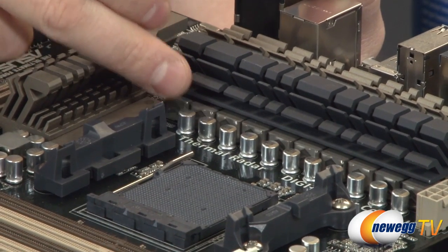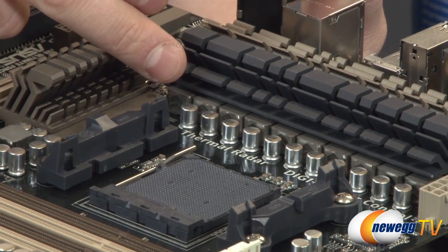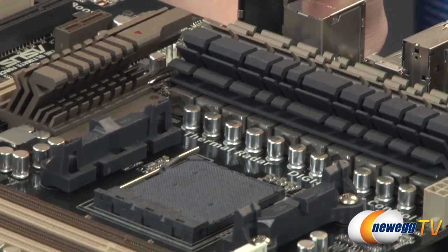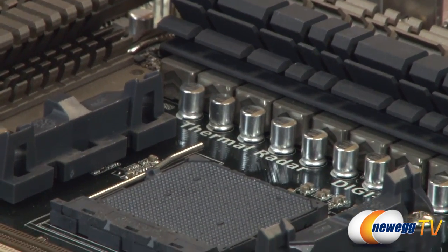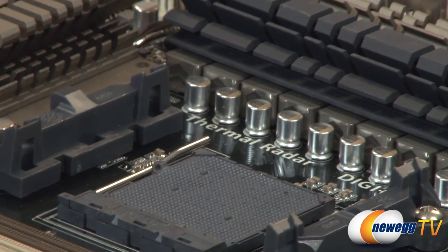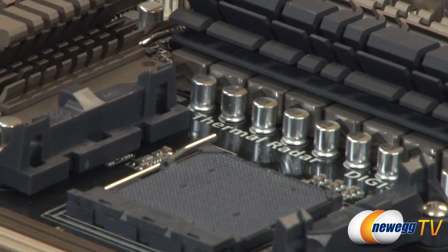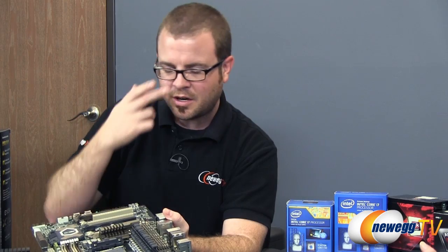The chokes are those little square pieces that you can see sitting right underneath it, and the caps are the cylindrical capacitors that you see on there. Those basically handle the transfer of the power from where it comes into the motherboard via the power connectors to the CPU itself. And again, that's an area where you'll see much beefier designs when it comes to overclocking motherboards, whereas with a non-overclocking motherboard, you'll have a simpler design, but it will always be designed to fit within that envelope that the CPU is supposed to run at.